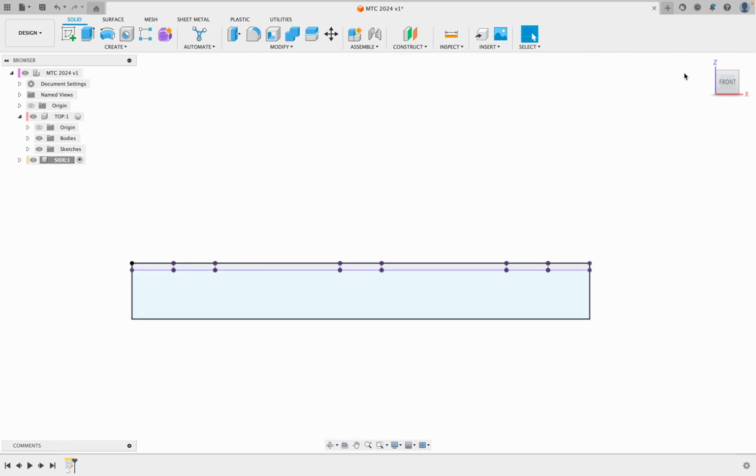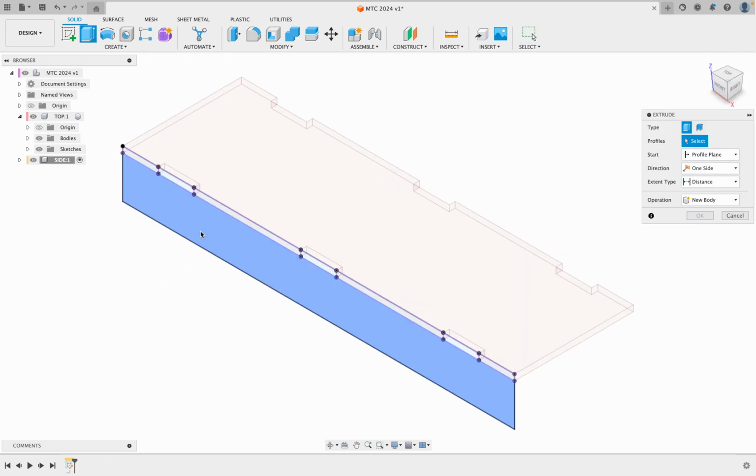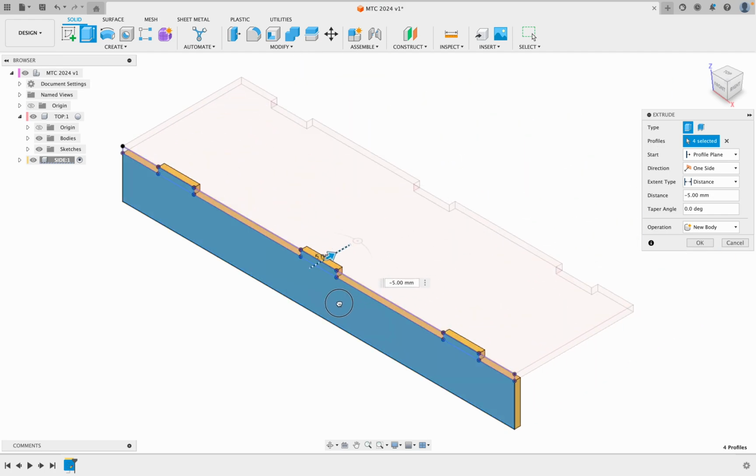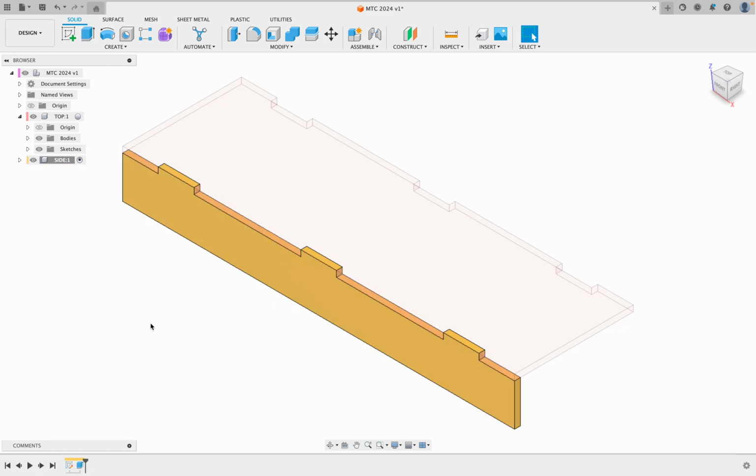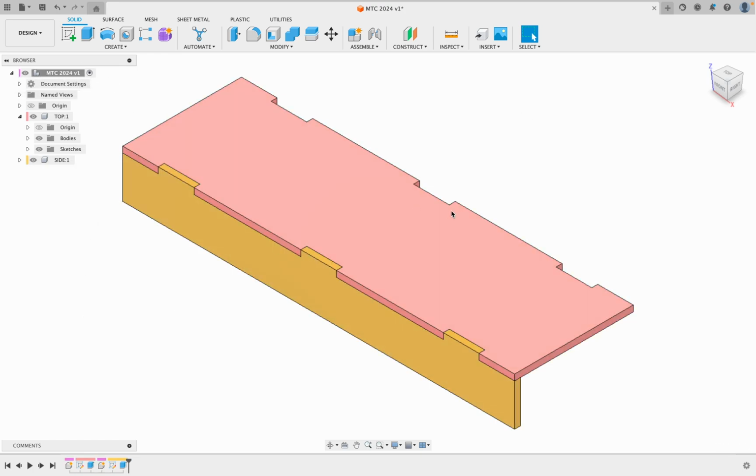All right, now I'm gonna finish my sketch. Okay, now I want to extrude. I'm gonna home view, E for extrude, boom, boom, boom, oh, boom, and boom. You got 3. I have 4 different parts here. I'm gonna drag inward. You can see what that does. Okay, not outward. I want to drag inward, -5 for me, and new body. Click OK.